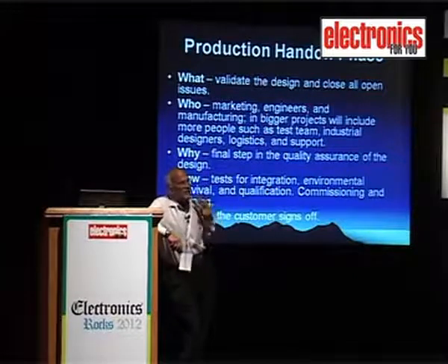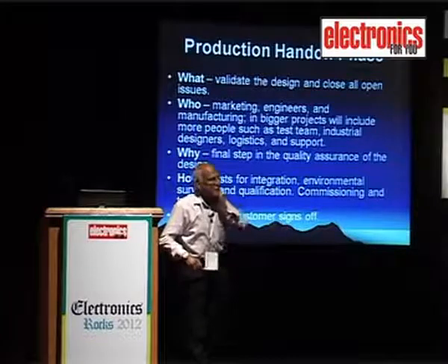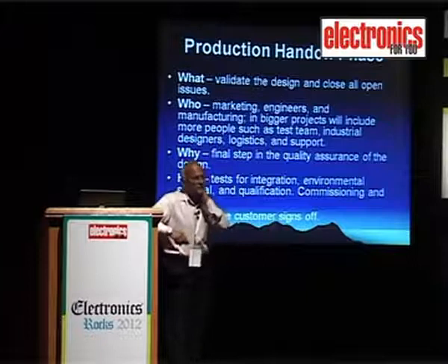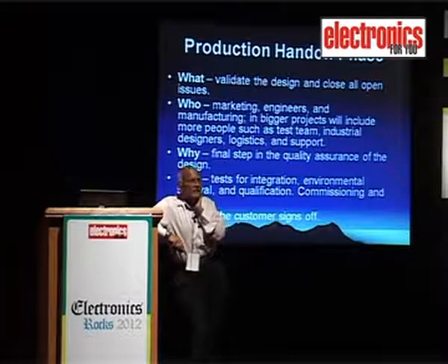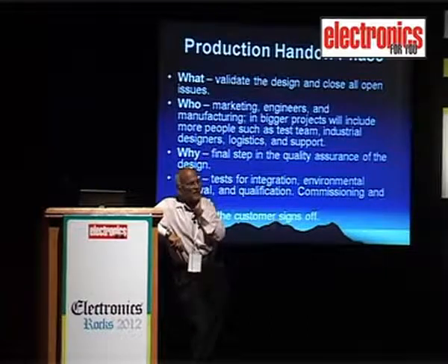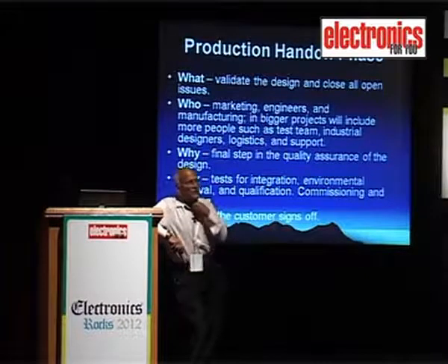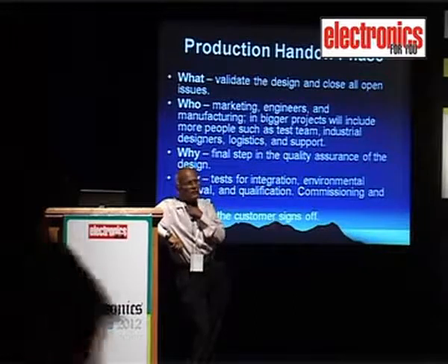It's for us when we tried to do a system in 1989 for remote control of electric substations through telephone wires, where Bombay's substations supply 33 kV to 11 kV and 11 kV down onto the streets. We had around 22 stations controlling around 600 odd breakers remotely through telephones.